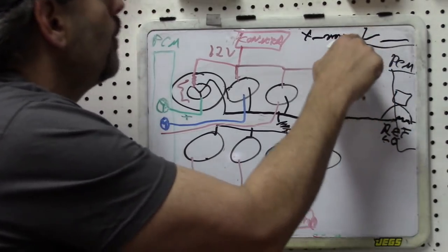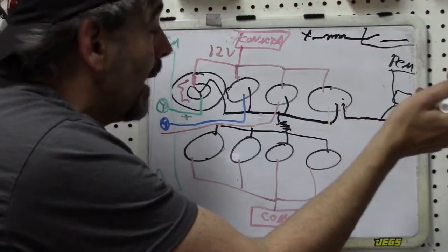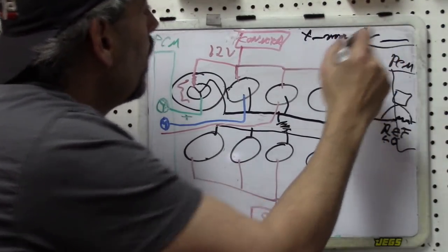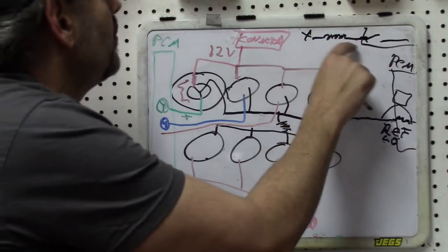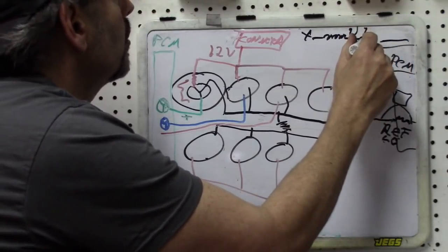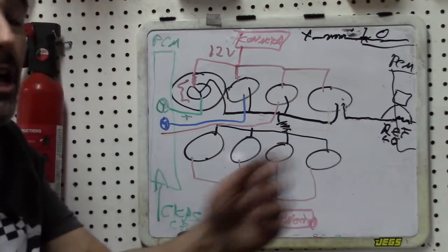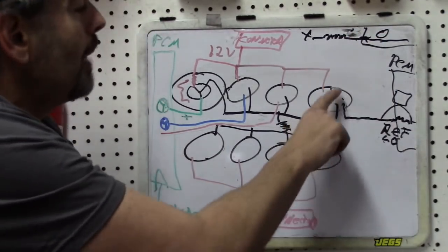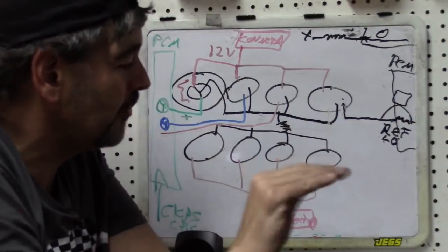Well, the trouble is if we were going to monitor this using the tactic that we talked about is commonly used with sensors, and we put a resistor here, well, the trouble is now with a resistor here, we wouldn't have zero voltage when the switch closes, right? We would have voltage here and then zero after. So that should easily make sense to you guys now. That's why I believe this reference low probably isn't a straight ground.